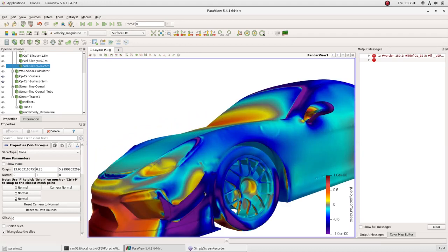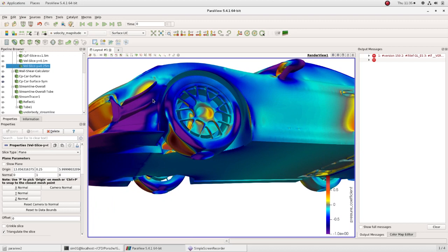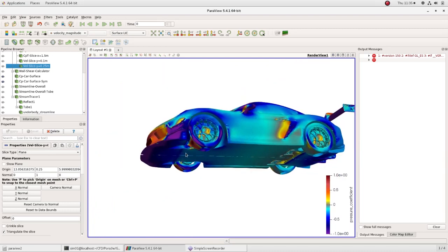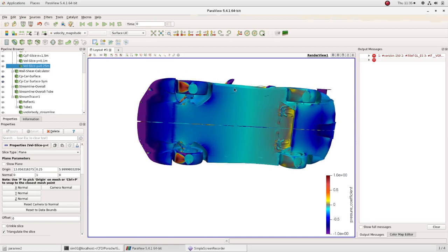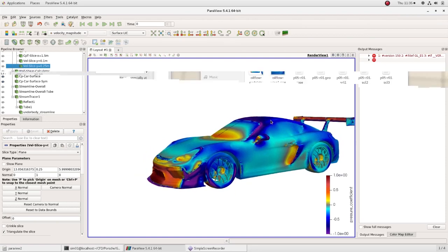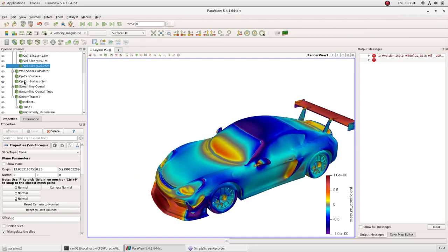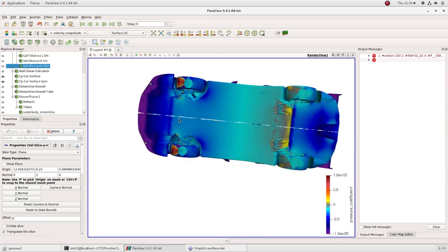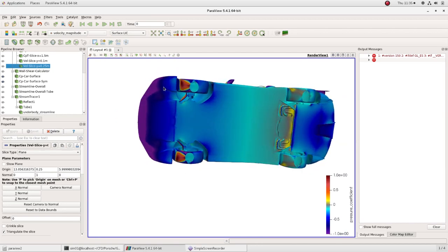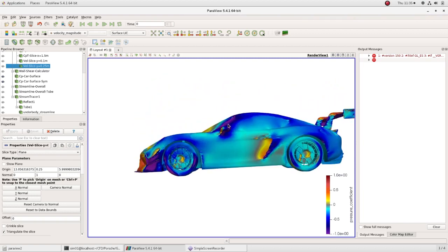This is caused by the dive planes themselves and the relative high velocity around the side of the bumper. This high velocity is one of the reasons dive planes, or canards, whatever you want to call them, can have high angles of attack and keep flow attached. The bottom side of the splitter is shown where it has lots of low pressure. You can see how the front diffusers affect the rest of the flow field.